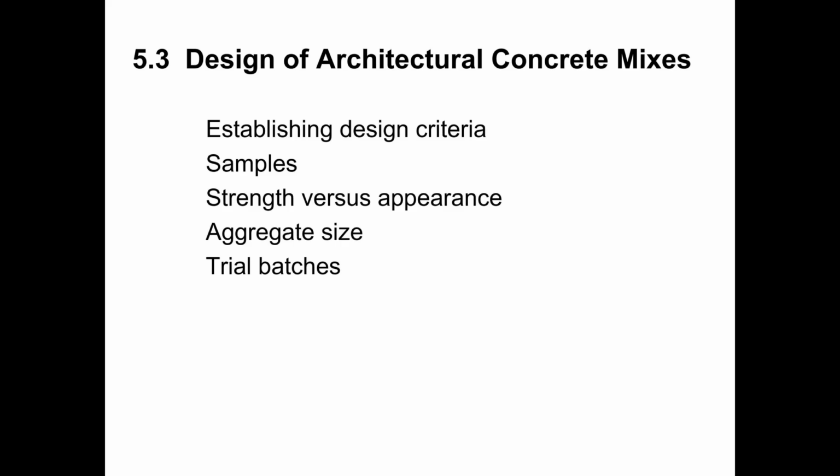The mix design does need to be approved prior to going into production. If you go into production with an architectural mix design that has not been approved, then there are risks associated with that. There's also absorption testing that needs to be done for architectural face mixes.